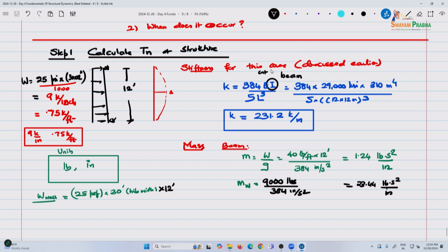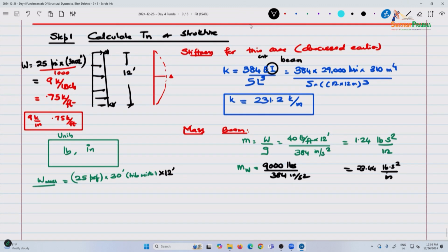How much it contributes to stiffness depends on whether it's a composite construction. You're not going to do composite construction there. So, the stiffness contribution can be taken to be 0, but the mass contribution can be accounted for. We'll do this calculation. I don't have it, but let's keep this in mind.